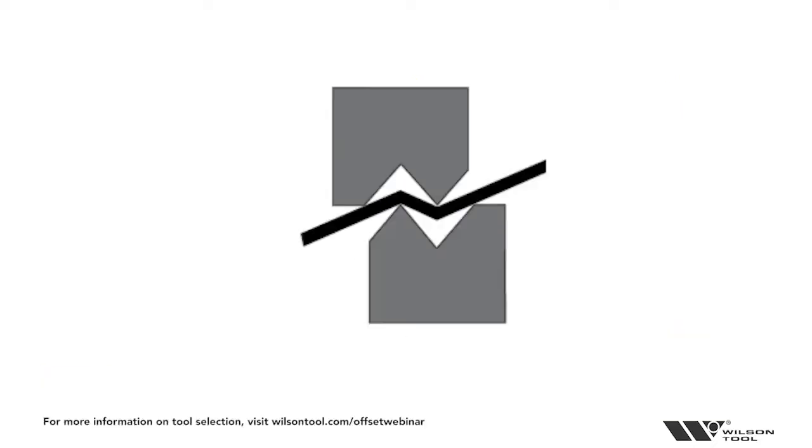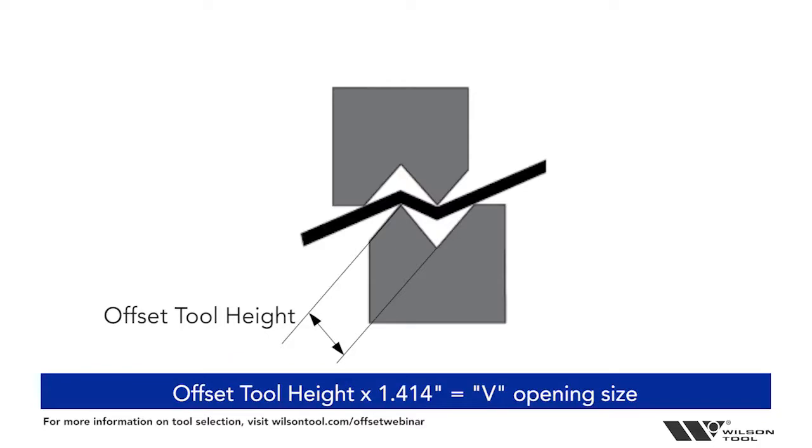Now let's just make sure we have the right tool really quick. Okay, there's a whole webinar on this, so I'm not going to go through this too much, but I will say if you're going to use a 313 offset tool, we're going to want to multiply that dimension by 1.414 to get our actual V opening size.